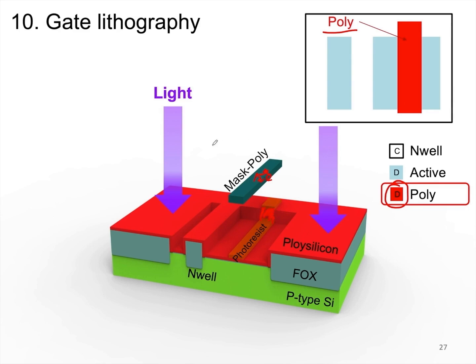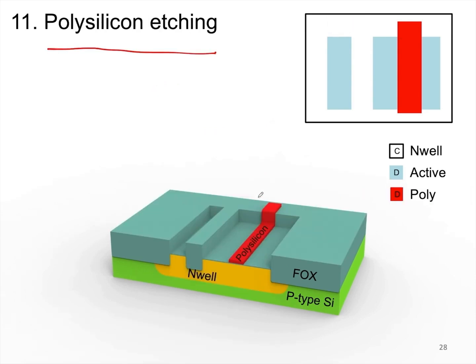When it comes to photoresist, it forms a shape that, if you were to make a cross section from this side, would look like this. This shape has photoresist at the bend as well, so after we go through the polysilicon process, the polysilicon pattern grows like this. From this image, you can also see that the layers we previously discussed, the layout of these layers, are all two-dimensional images, but they actually reflect a three-dimensional structure of our integrated circuit, right? So you can see this is the gate we designed, and this is the actual processed gate. You can see the correspondence between them, right?